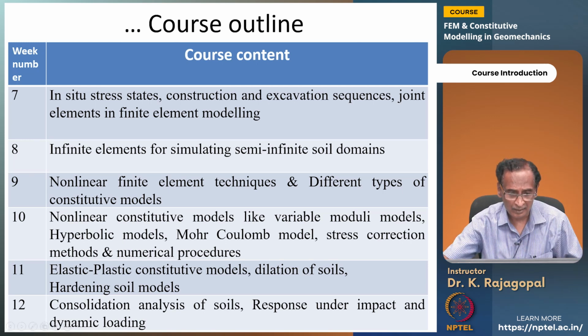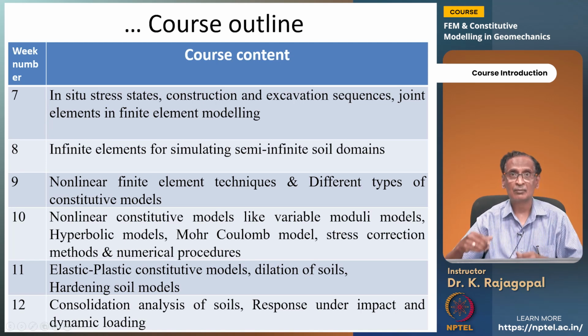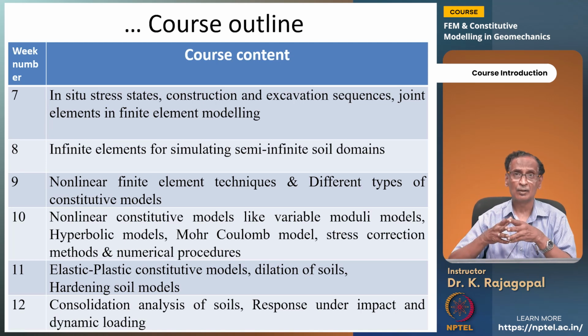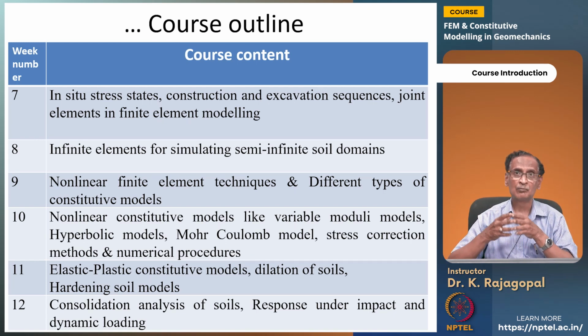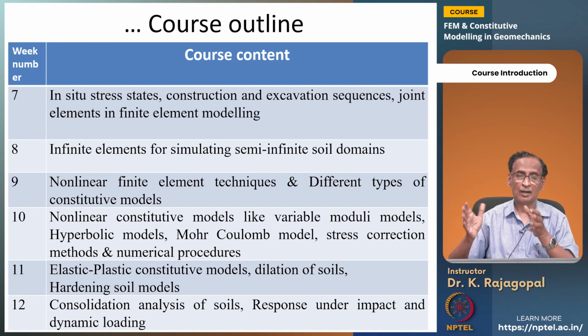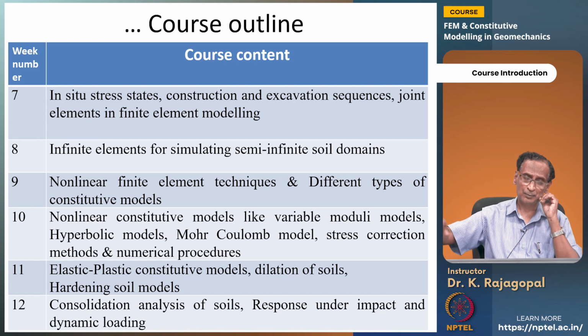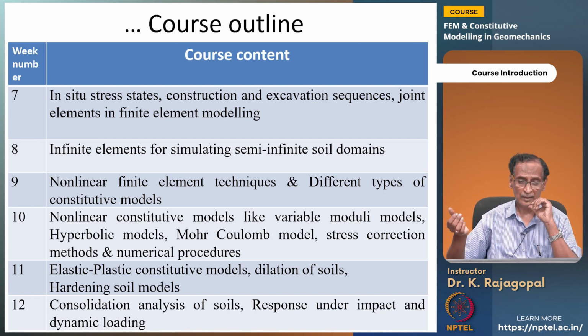And then elastoplastic constitutive models, and how to incorporate the dilation of the soil, because dilation is the volume increase under shear strain. If you have a linear elastic or a nonlinear elastic material, the shear and normal strains and the shear and normal stresses are decoupled, they are not related to each other. If you apply a pure shear strain, you will develop only pure shear stress.